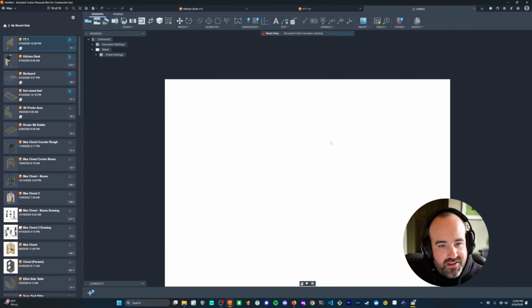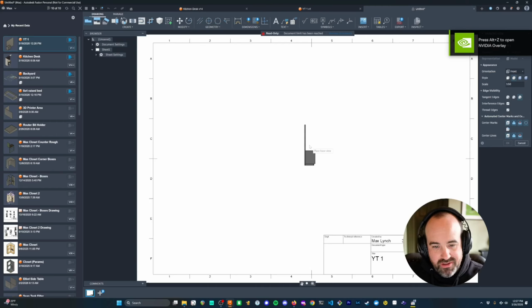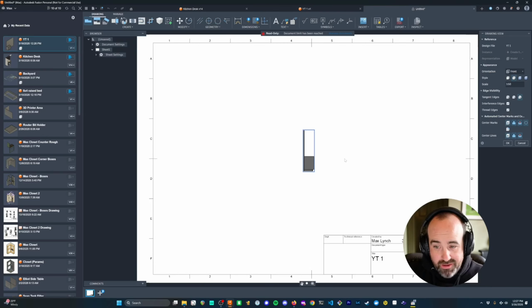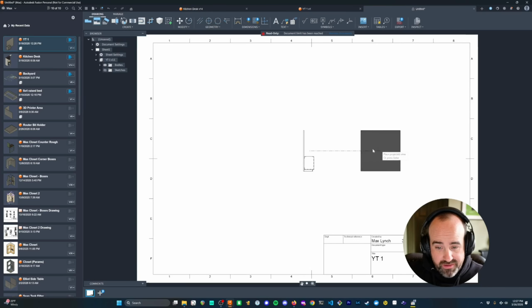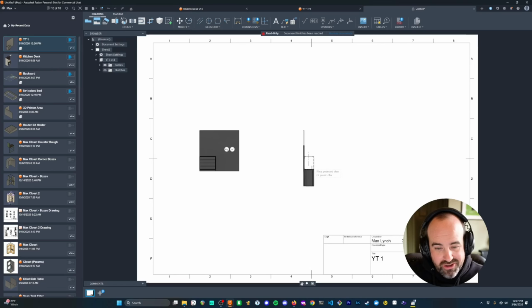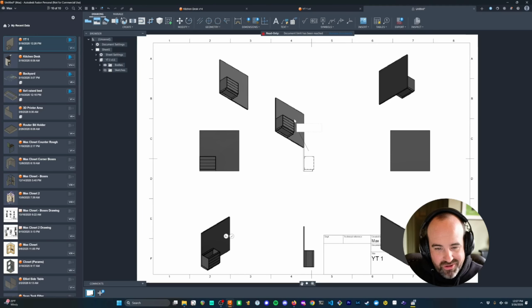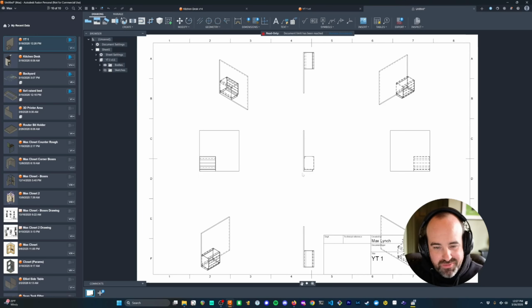The drawing takes a reference project and lets you actually lay it out in 2 dimensions or 3 dimensions with like a perspective drawing. So to start, you place the base view, and then you can go and do projected views from this of different sides of the design. So I usually just click and I go in a circle, and then it's going to force you to have those perspectives.